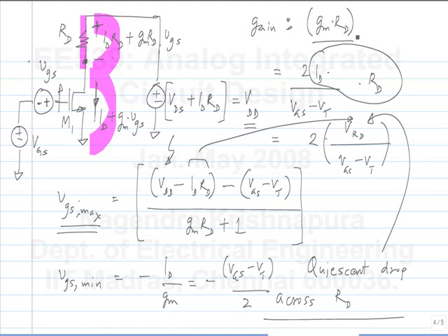And we also know how to control the gain. We either have to increase the quiescent drop across RD or reduce the value of VGS minus VT. Okay. What is the consequence of reducing VGS minus VT? The FT of the transistor reduces, right? FT is directly proportional to VGS minus VT. So, if you try to get large gains by biasing it at a smaller VGS minus VT, you will end up with slower transistors, which is basically the same as saying the transistor gets longer or bigger or whatever. Okay. So, there is some trade-off between trying to get larger and larger gains from a single stage and getting higher and higher speeds. Okay. Right now, we have not evaluated the speed of this amplifier. So, I am talking about the intrinsic speed of the MOSFET. Okay. That reduces if you operate it at a smaller VGS minus VT.